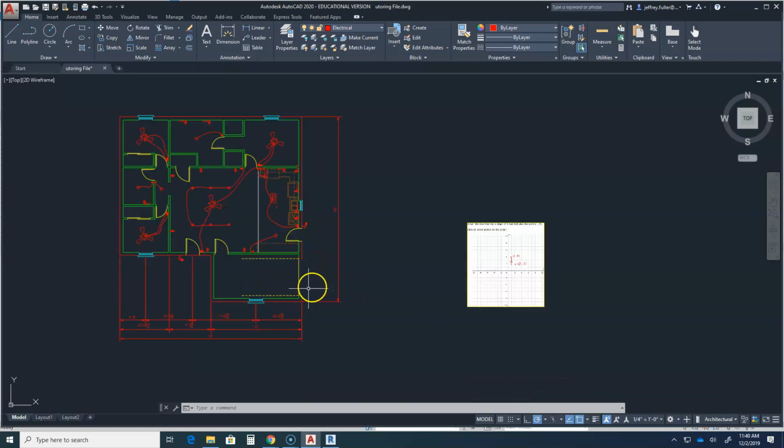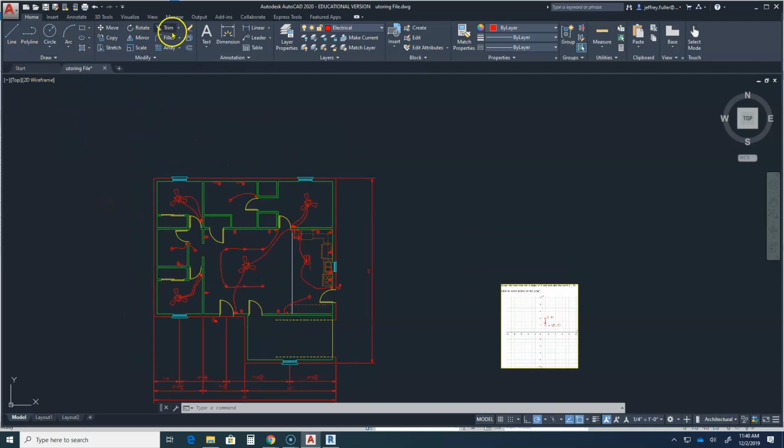I'm going to again do the next level, which is going to be minor or major walls, and then doors and windows. I'm going to go all the way around doing the same thing. Now, when I get up top, that's when your directions will change a little bit. I'm going to do an overall, and you see I'm pulling the dimension line up. That is in the Y direction, so that is going to be X 0. So again, I type at 0 in the X, tab 8 feet in the Y. So that's in the positive direction for the Y.